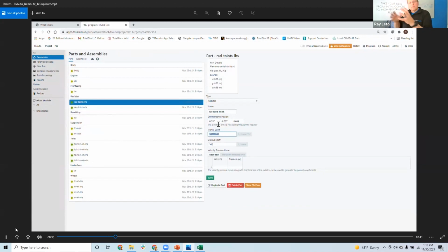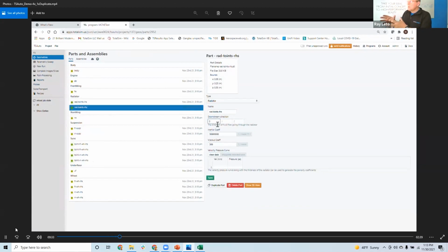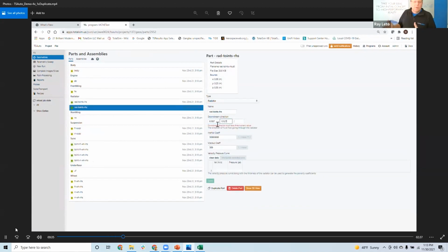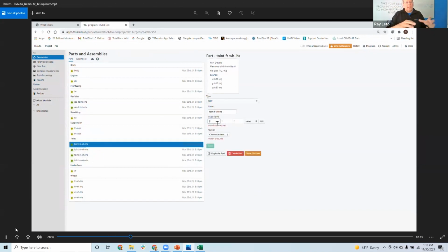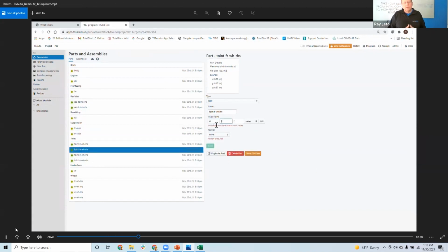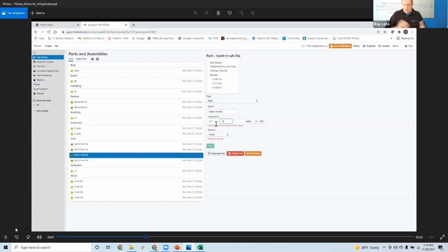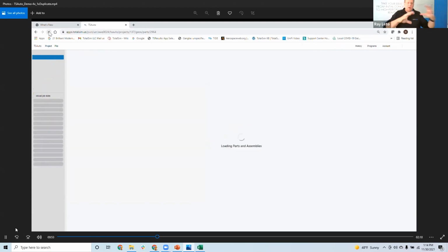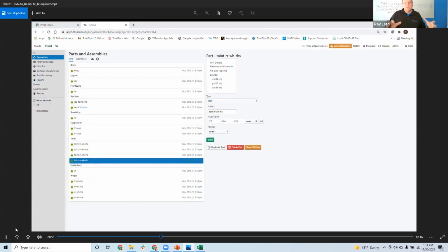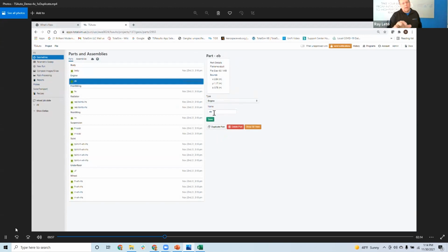We have to take the data from the CAD or the known data that we've got from scanning and tell the computer where things are located. The radiators, for instance, we have to describe the characteristics of the radiators. We have to describe where the wheels are and where the rotation center is. All the typical engineering things that you would have to do, like even in a lap sim, like Danny was showing yesterday, that you have to have all those points and understand them and input that. So that's what we're doing here.